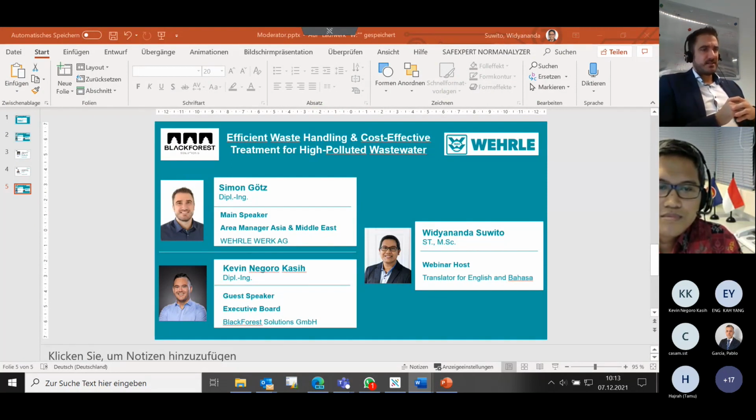A biomembrane system, for example, can handle 1,000, 2,000 milligram per liter of suspended solids, compared to a direct reverse osmosis, which is limited, let's say, to 30 or 40 milligram per liter TSS. That means the pre-treatment for a direct reverse osmosis system must be more carefully chosen and maybe more sophisticated than for the really robust biomembrane system.